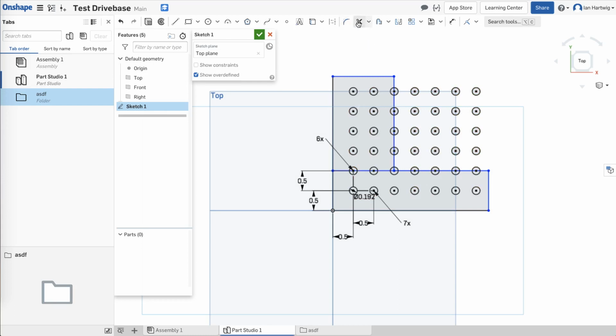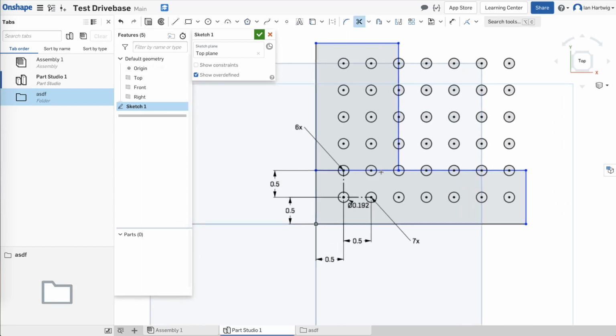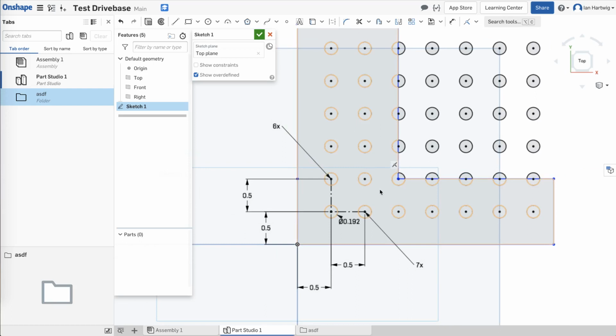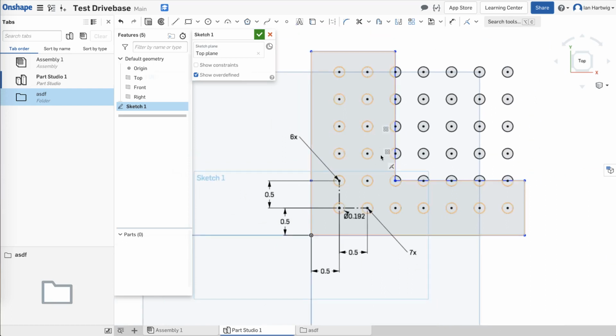There's a bunch of helpful tools that help you manipulate lines automatically, things like offset, drawing slots, mirrors, extend, but let's use the trim tool here. I'm going to basically slice this section of the line out, and what that's left us with is I can now delete this section. So the trim will truncate a line where it's crossed by other lines. And so what that helpfully left us with is this L-shaped area.